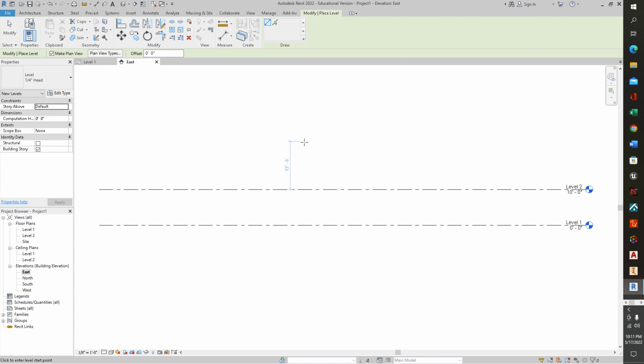It'll bring up the level lines command. We could just draw in level lines at whatever height, and it will give us the height. You can see the phantom line that's growing, and I've got one now. It says it's 12 feet up. We could draw a line up 12 feet or whatever it might be by dragging it across, and it shows me that that's at 23 feet.